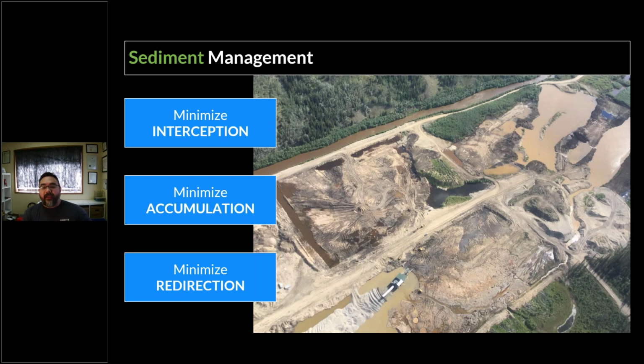At the planning and locating side, that means understanding the superficial materials, reviewing the geology and knowing what's coming, and finding the specific features that may be less erodible, because we know that forest roads or resource roads and crossings, whether it's bridges or culverts, are sources of sediment.